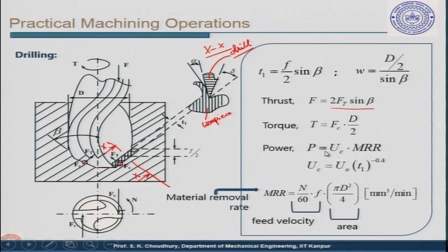Now, the power is given the same way as in the case of turning, shaping and planing. So, it is given by specific energy into material removal rate.